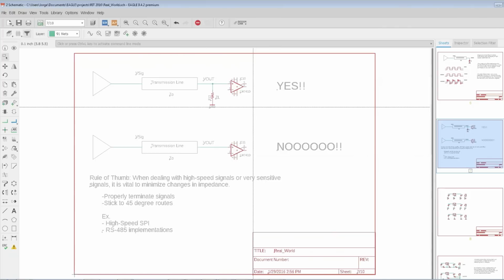The reason for this is to minimize inductance, to minimize impedance. Water flows through the path of least resistance. Current flows through the path of least impedance, always. And the path of least impedance occurs closest to the signal trace, right underneath it.